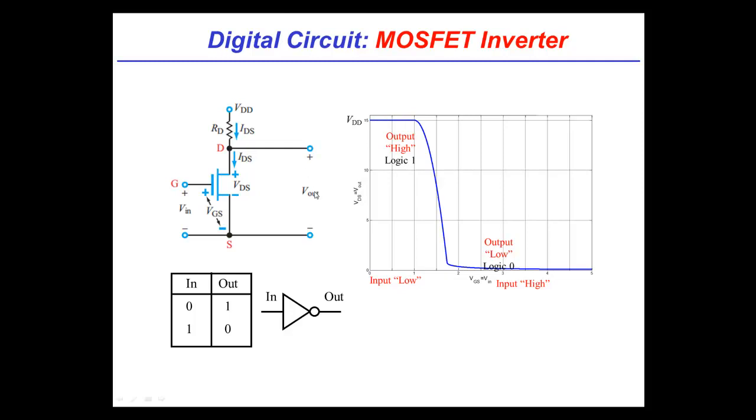Another point that you brought out that's really neat is you said as long as there's no load. And the cool thing about MOSFETs, as you pointed out to us at the beginning, is that there's no resistive path through the gate. So if there's a MOSFET at the output, it actually doesn't load this very much. And that's one of the fundamental reasons why MOSFETs have been so instrumental, that I can stack them and they don't influence each other's inputs, each other's outputs with their inputs. You'll run into this in your digital classes. We don't have to belabor it, but it's a very cool little detail.